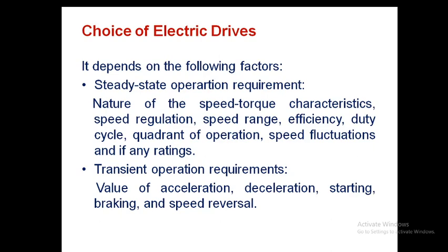Among the four quadrants of operation, whether we need only motoring, braking, or reverse motoring, reverse braking also, like that quadrant of operation, speed fluctuations, and any other ratings. So depending on the steady state operation requirements, we need to choose the proper electric drive.